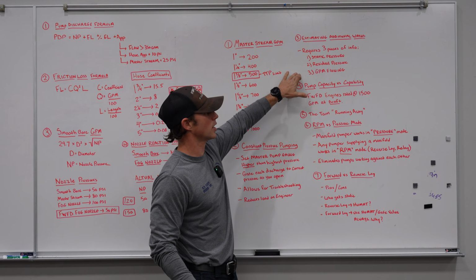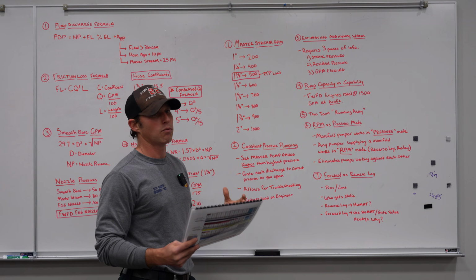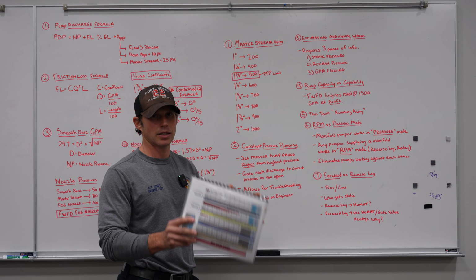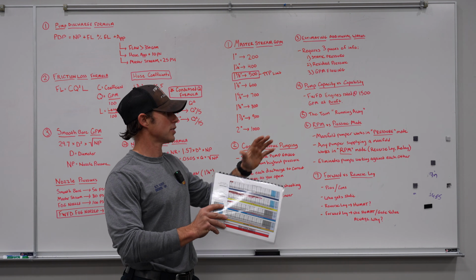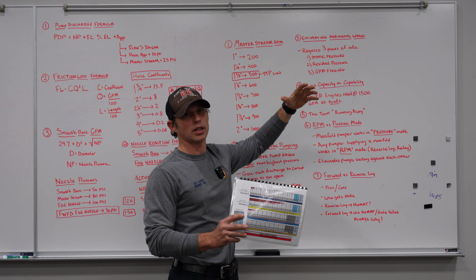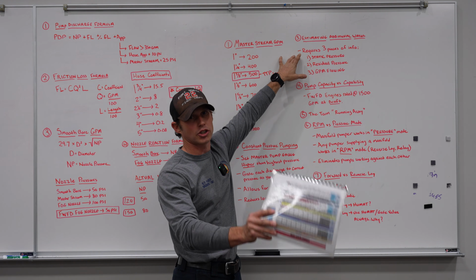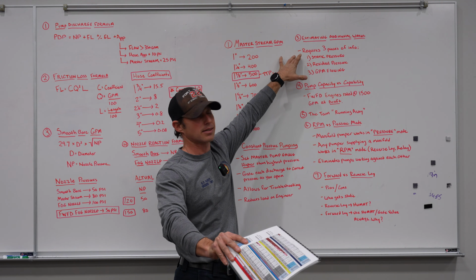And the third piece is going to be your gallons per minute flowing. So that's going to be the amount of water that you're actually flowing at that given time. So obviously remember that this is dynamic. This is constantly changing based on opening and closing lines. So your static is going to be the same no matter what. Once you get your original static, your static stays the same.